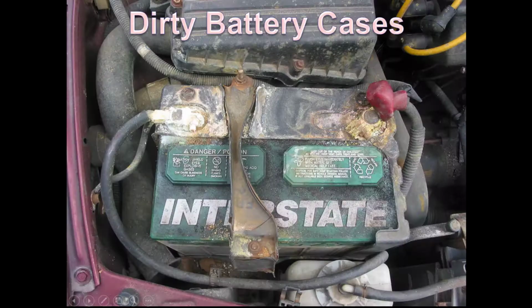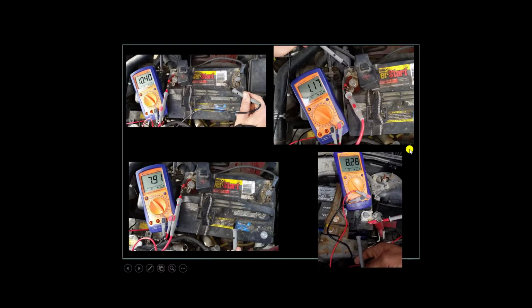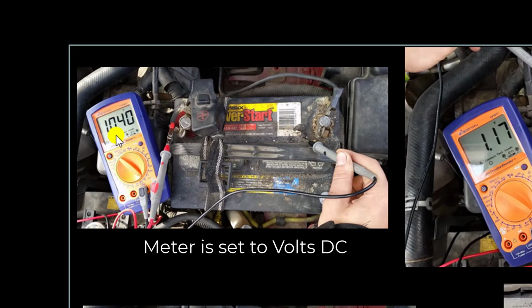Here's an example of a dirty battery case. Dirt itself contains conductive material. So in this example, I have a meter that's not a snap-on meter, but you can see in these examples, I'm connected to the positive terminal with one clip, and my negative lead is just touching the dirt on top of the battery, and it's giving us a voltage drop, an extension of that negative terminal.